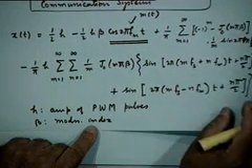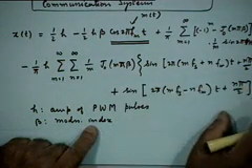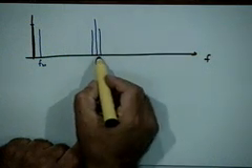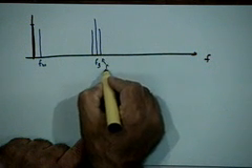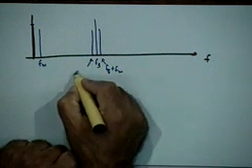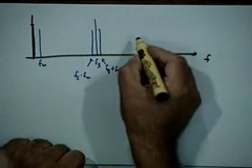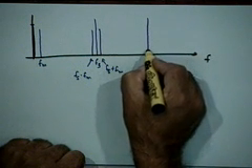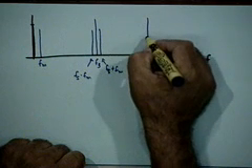So when beta is very, very small, that is you are using only a fraction of the maximum possible width that you can have, right? When beta is very small, then around fs also you have only two components, namely fs plus fm. It's like narrowband FM. It becomes like narrowband FM. So fs plus fm and fs minus fm, and then you have components around 2 fs, and these amplitudes will be different, and so on.